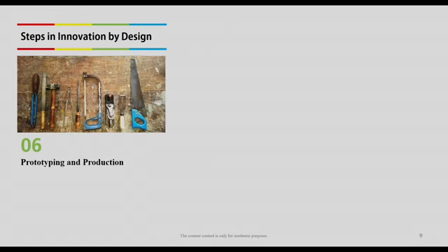The next phase is prototyping and production. The final concept is further modified according to material and manufacturing limitations. A designer then makes CAD models, mock-up models, and functional prototypes to get feedback from the user, based on which further modification is done. After selecting the final prototype, the design goes for production. So, here the process is very iterative.